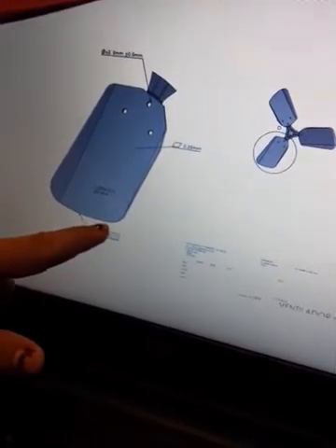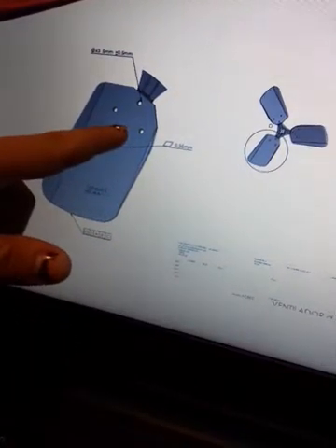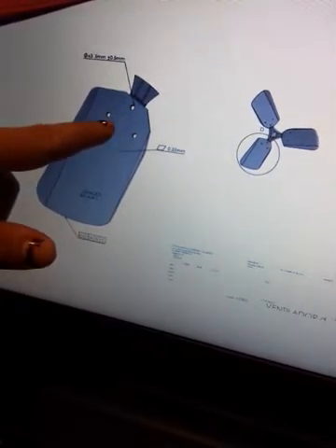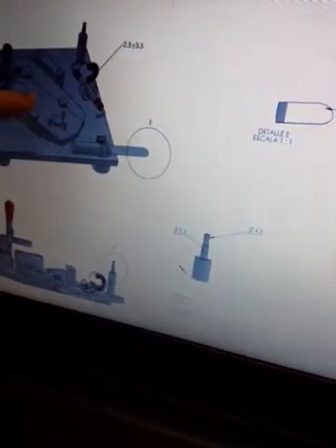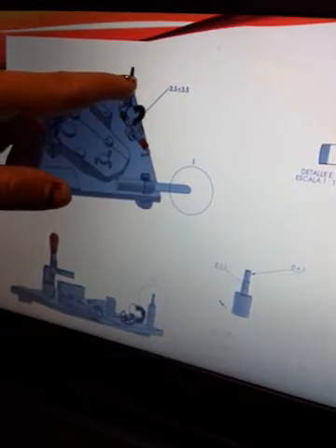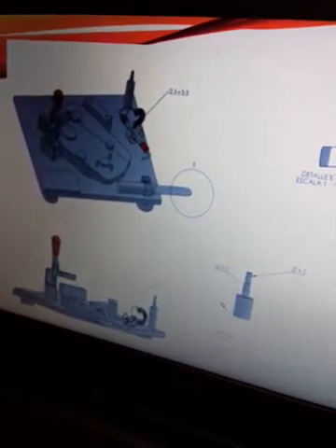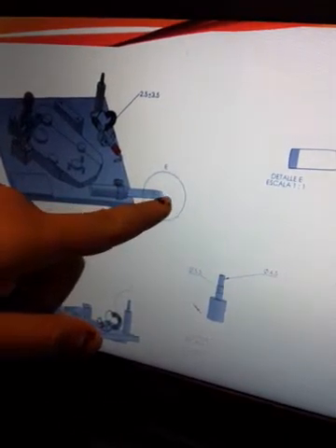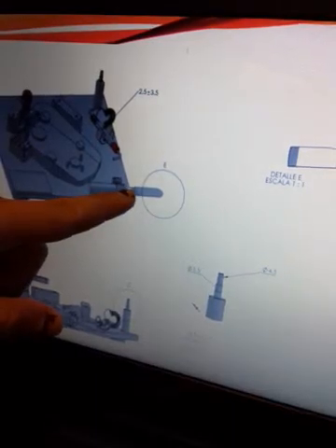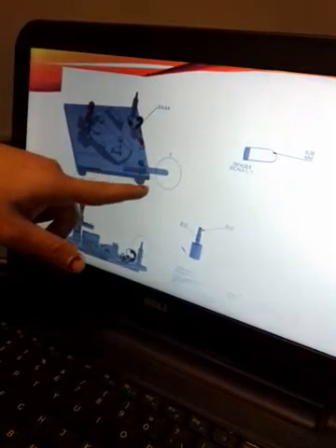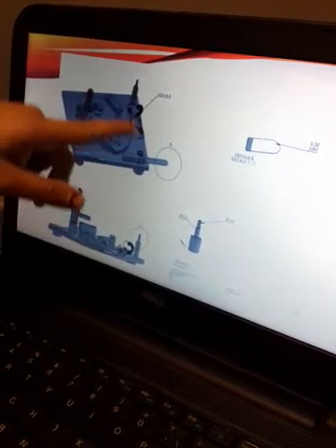So you can see here, this is the important part that we need to measure in a dimensional measurement: the blades of the fan. The blade has 3 holes, and for these 3 holes, in the next slide, with this go or no-go gauge you can measure, and this is calibrated in a dimensional laboratory. And with this part we can measure the thickness. This is all the fixture.